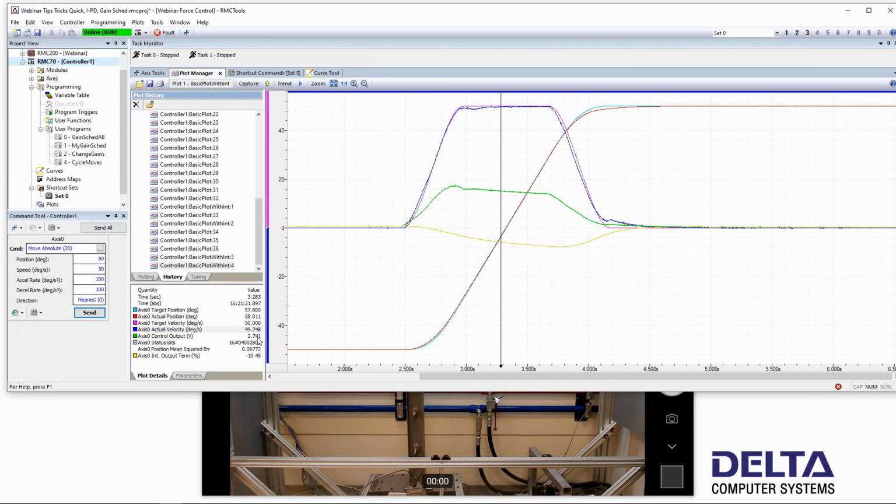And then I take my control output, that would be 2.7 volts, is 27% divided by pretty much the same velocity. So that's 27 divided by 50 roughly. And then I can move it here and I can do the same thing. The control output is 2.8 volts or 28% divided by about 49 looks like.